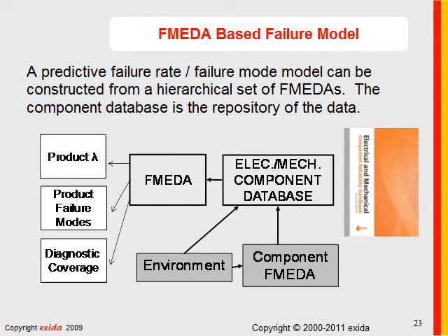However, redundancies in a design can be dealt with by replacing redundant components with a single component and using the common cause failure rate. Common cause failures can be modeled. There's a very simple chart to use for that purpose in IEC 61508 Part 6. And via that simple technique, redundancies within a product can be modeled within an FMEA. Need more information on that? Send me an email. Thanks for the question.